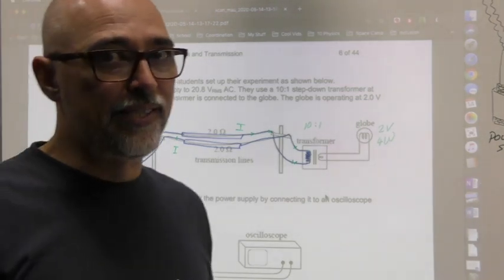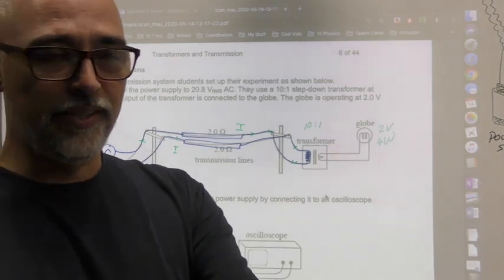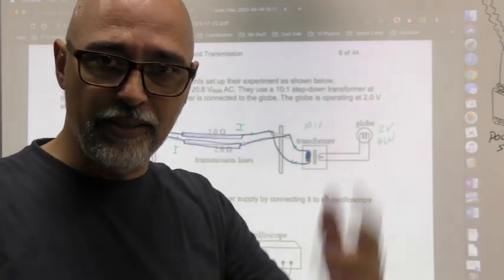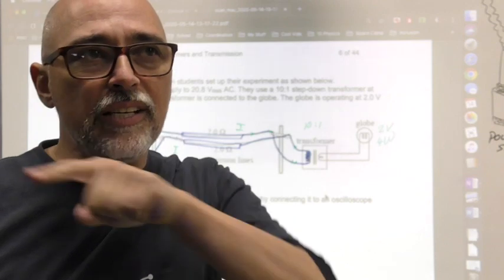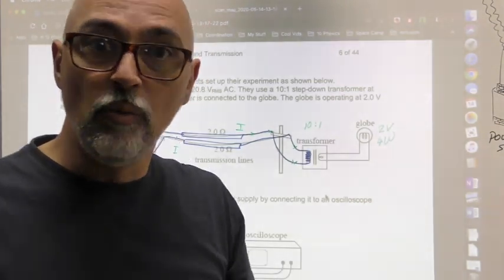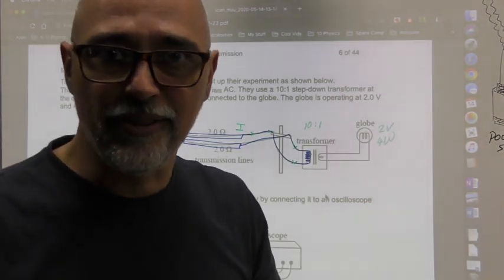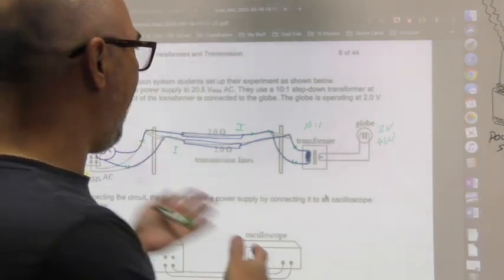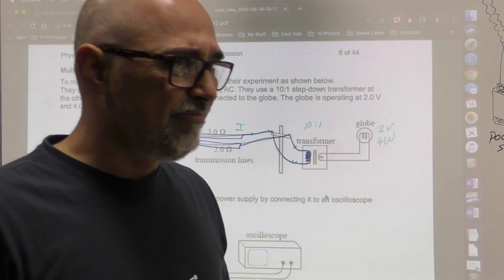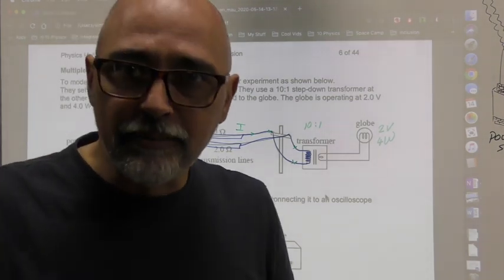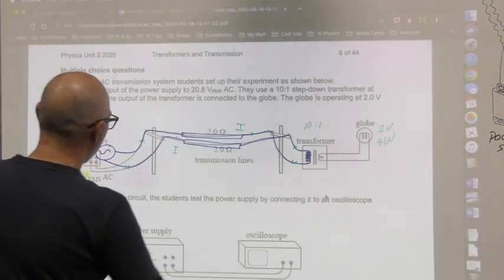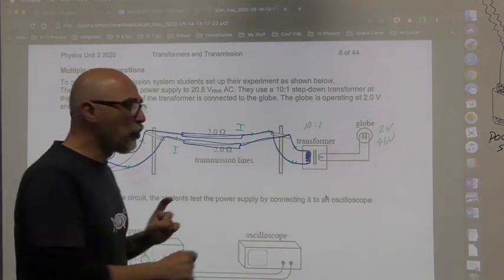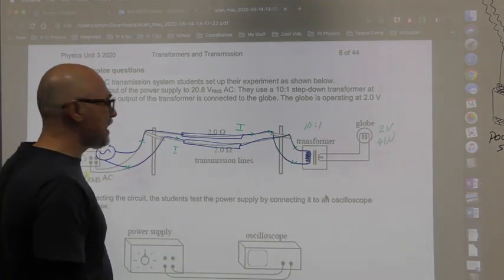What are the rules of a series circuit? Well, each component will drop a certain amount of voltage depending on its resistance, but what's the current in the circuit? Well, it's the same everywhere. Why? Because the current's made of electrons. You either have an electron or you don't. It's not like they disappear.